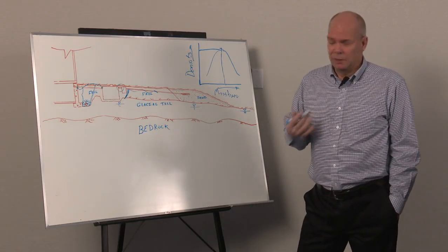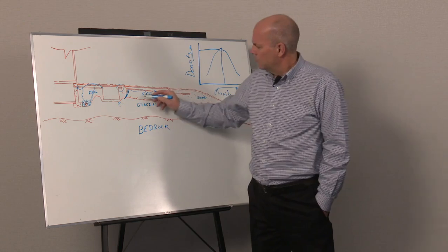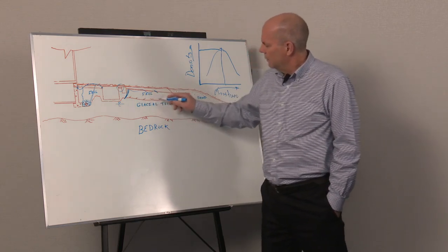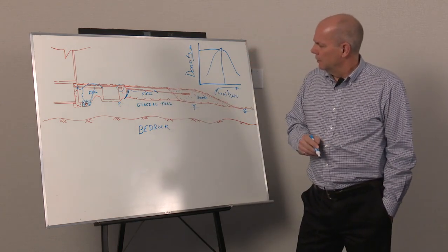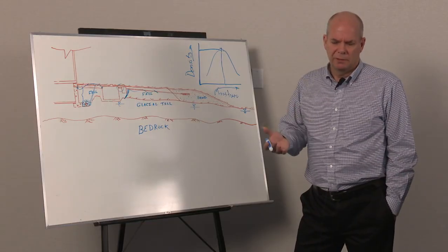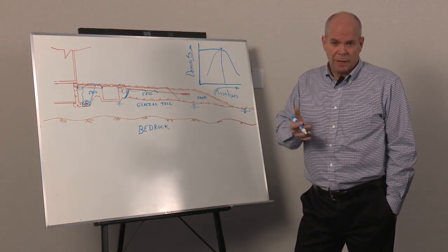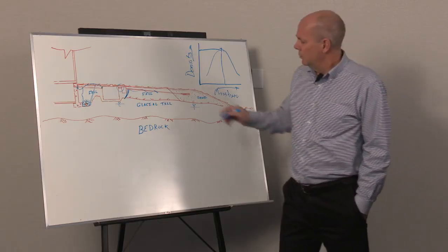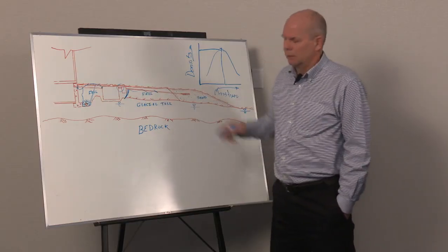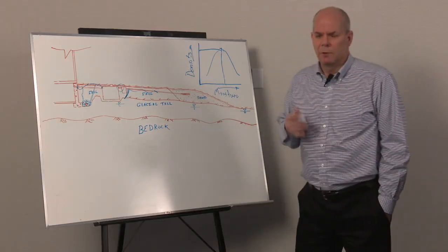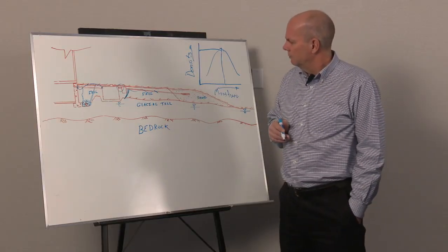And that may mean if it's garbage, which a lot of times it would be, and at the base of it, they may not have grubbed the original ground surface, so you've got stumps, you've got maybe wet, peaty, boggy areas. You should have good, competent ground below your pipe, or else you run the risk of getting settlement.